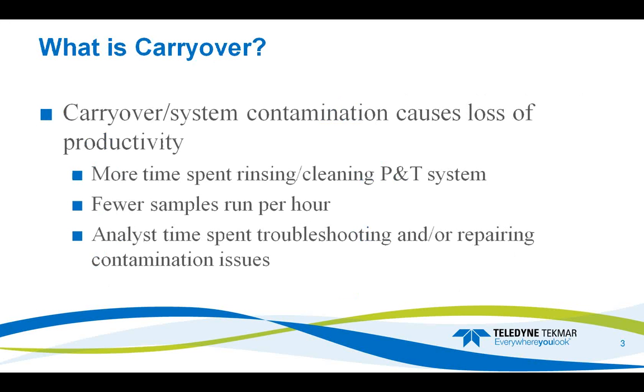Okay, so starting, what is carryover? Carryover is any time we are seeing some of our target compounds moving from one sample to the next. So for instance, if we were to run a high concentration standard and then the blank immediately following had some target compounds in it, that would be carryover.